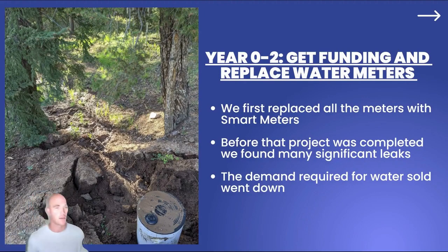We came back with a smart metering system. So now, instead of the operator having to crawl up into these spaces and go into people's houses to check how much water they use, he can just drive by with a radio and it would pick it up. They were in a more remote location, so at that time, that was the best way for them to monitor them. And before we even finished putting in these meters, we were finding significant leaks in different service lines, and they were small ones, and we were able to fix some of them on point or identify the owner.